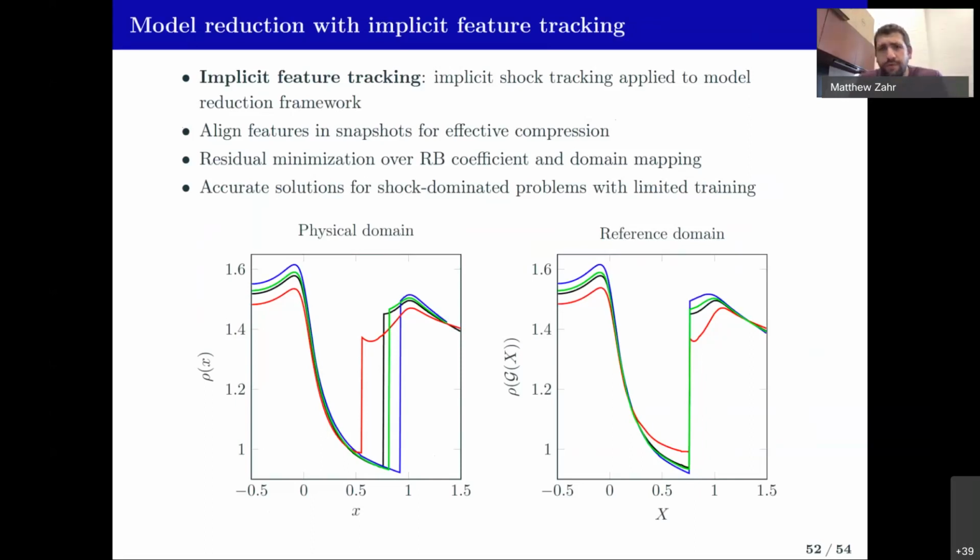But the problem with that is that if you have a shock that moves a large portion of the domain, whatever elements track the shock at time 0, you have to pull those elements along the whole way, or you have to do some more complicated solution transfer between meshes as you pass the shock off between elements. So what we've done so far is you just track at time 0, or at whatever time the shock emerges, and then it's the same elements that track the shock all the time. Now, of course, if the shock moves a lot, then you can really screw up your mesh. So we don't really do the method of lines approach that much.